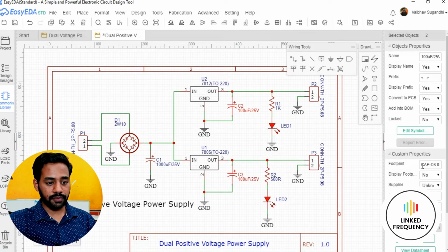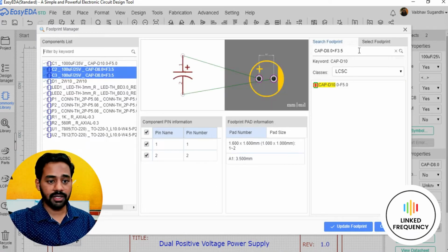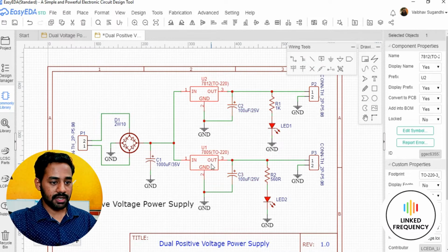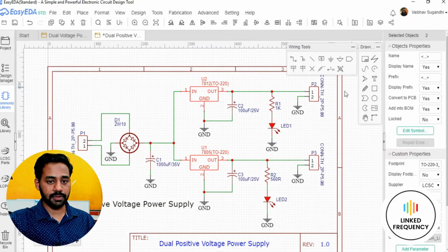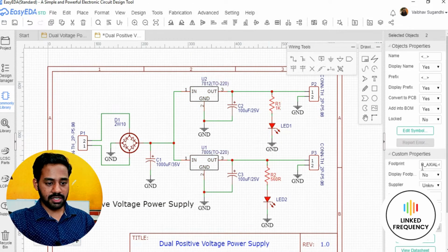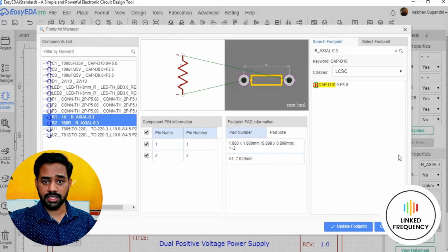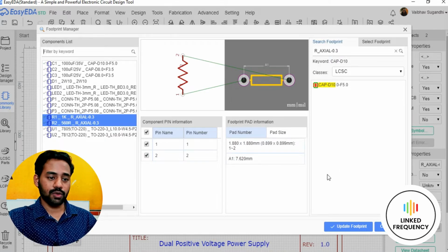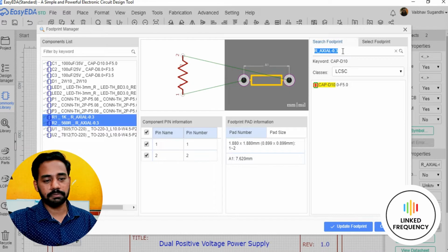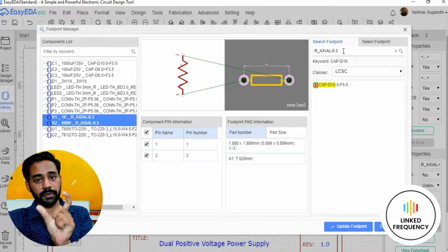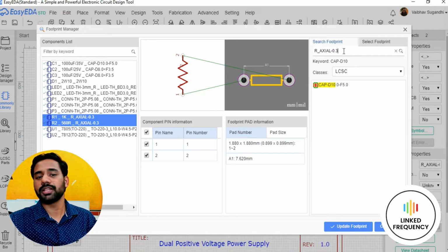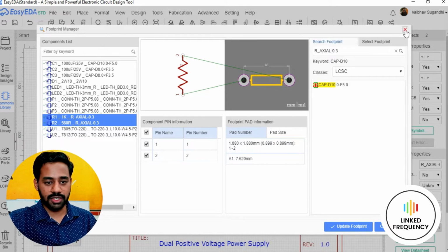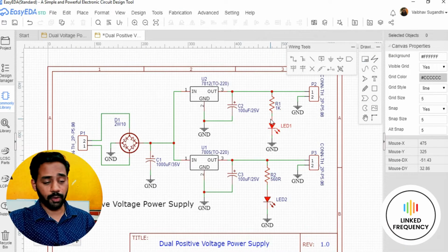And of course, the 100 microfarad capacitors both have an 8 mm diameter, which is absolutely fine. And then 7805 and 7812 both have a TO220 package. Again, these are absolutely fine. And now resistors. Both resistors use through hole technology. So RXCL 0.3 means 0.3 inch is the dimension, the distance between one pin and another pin, which is absolutely common with respect to the components available in the market. For the quarter watt resistors we are using, RXCL 0.3 is the selection.